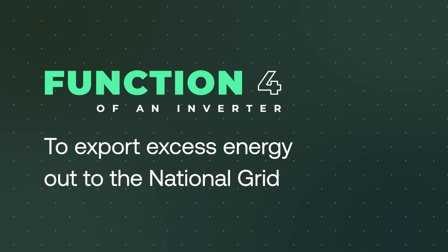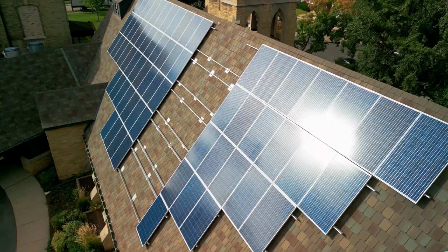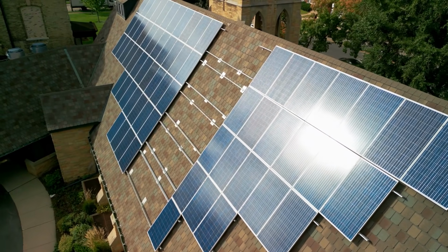So as engineers, we can write out to the grid, get permission to connect, and you can effectively be your own little power plant. And energy suppliers will effectively pay you a credit on your energy bill for every unit that you send out to the grid. So during the likes of summer months, you can build up a credit on your account, and then in the winter months, when you do need to still purchase energy, hopefully off peak into that battery, you can use that credit from the summer to offset against your winter debits.